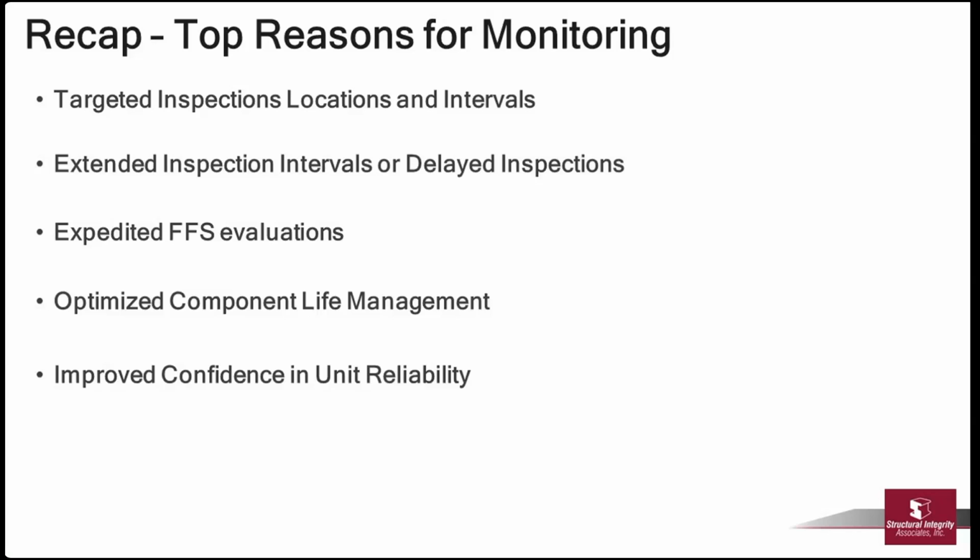And I think the trend in monitoring is going to continue. We talked a lot today about temperature sensors, but there certainly are other sensors out there, like ultrasonic sensors for spray lines to monitor flow through them, and sensors on drains to see if all your condensate has come out of the system.